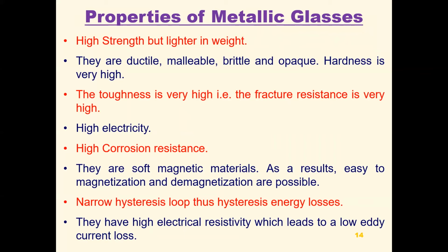High electrical resistivity, high corrosion resistance. They are soft magnetic materials. As a result, easy magnetization and demagnetization are possible. Narrow hysteresis loop, thus low hysteresis energy losses. They have high electrical resistivity, which leads to a low eddy current loss.